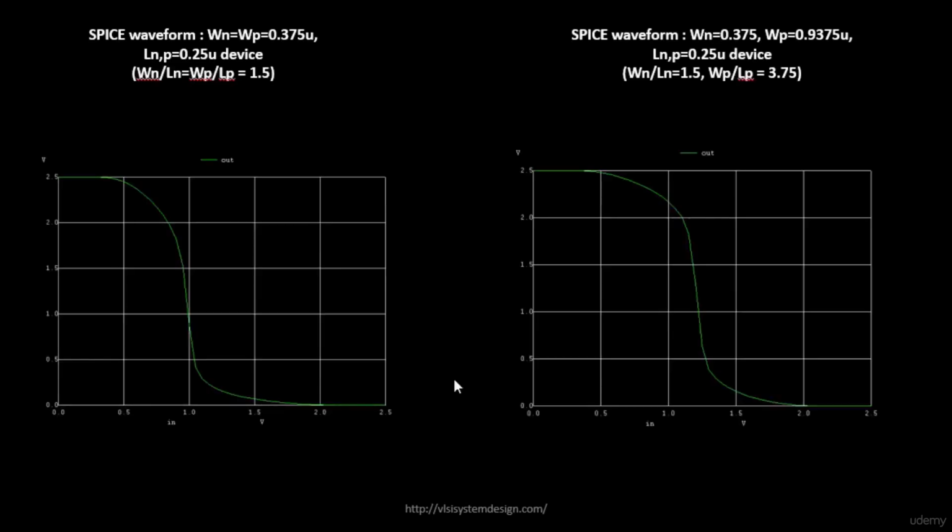So this was the waveform, and this was the waveform for a device where the PMOS was bigger than the NMOS. Clearly, if you see, the shapes of the waveforms are the same. If you see the shape of this one and the shape of this one, irrespective of the voltage levels at which they are switching, if you look just at the shape, they're almost the same. There are a few glitches in this region and this region, and also over here, but the shape remains the same. So what does this tell us? This tells us that the CMOS inverter is a very robust device.